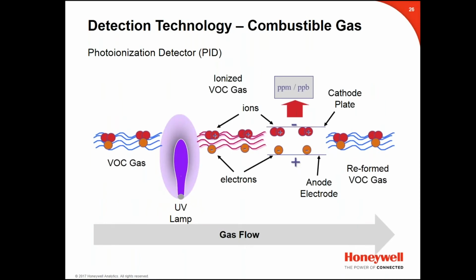This is a different technology. This is a photoionization detector. As organic materials decay and break down, they release volatile organic compounds in the form of VOC gases. These gases represent combustible and health hazards if they accumulate in sufficient quantities.